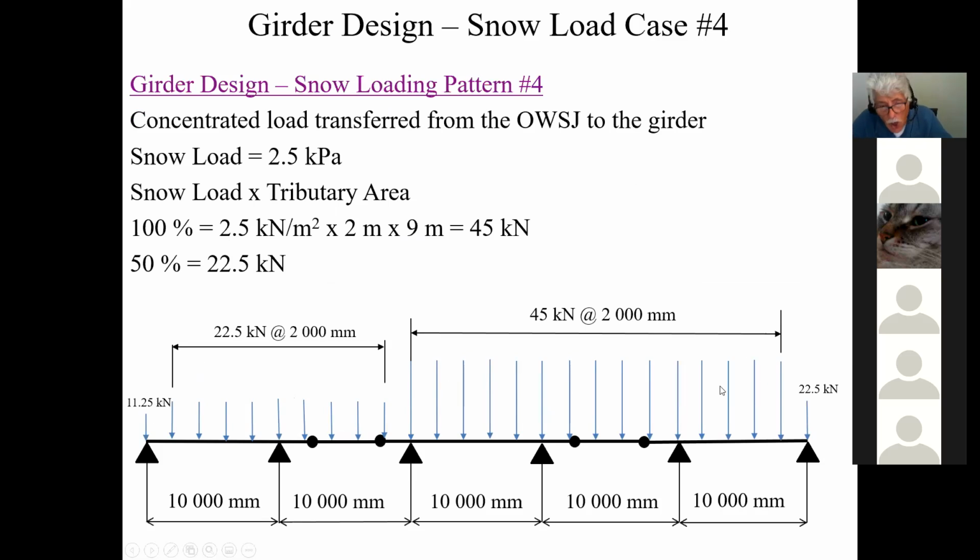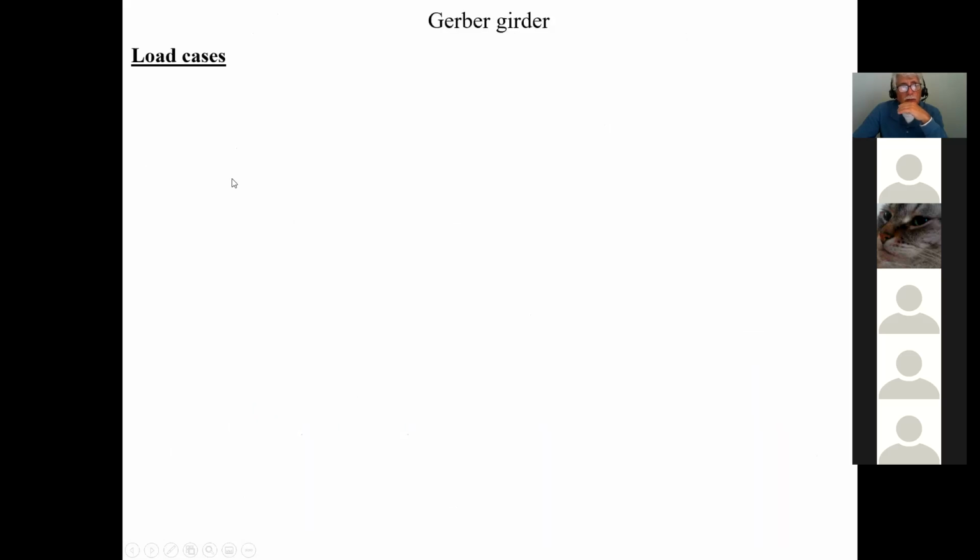So those are the 4 load cases that we're going to have to do in ADA. And then of course, as far as the load cases go, ADA has dead for self-weight. Don't change that. Leave dead for self-weight. Leave that load case as the program decides. Don't modify that. Some people modify that, I don't know why. Just simplify your life.